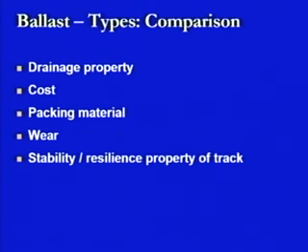In this case, obviously, materials like gravel, river pebble, or the crushed stone aggregates used from different locations have a higher value of stability as compared to the other ones. But if the compaction of the rest of the materials is also there, then they can also provide a good amount of stability.